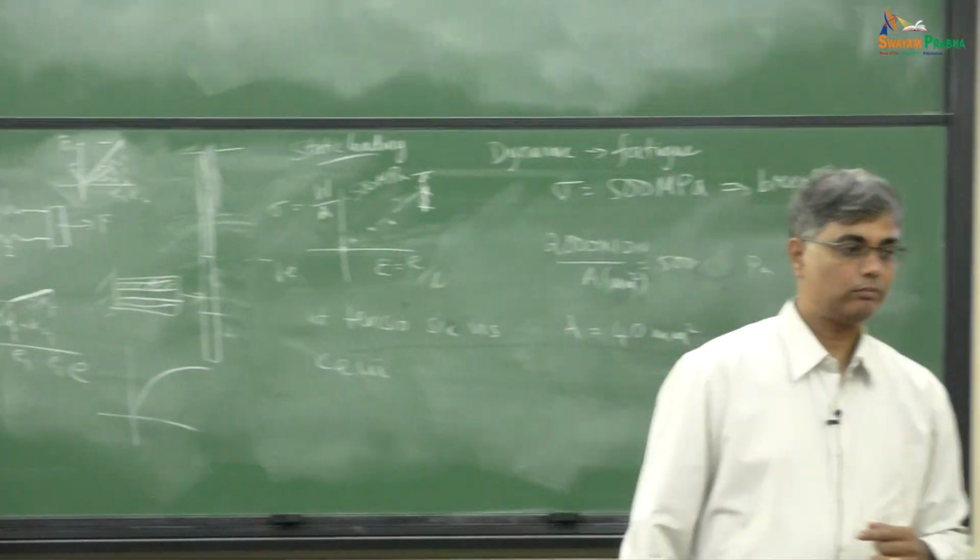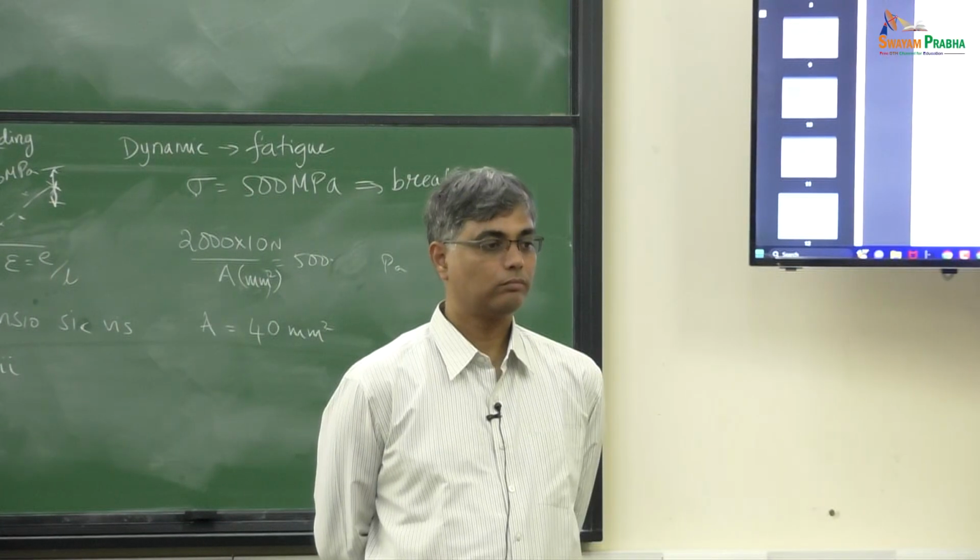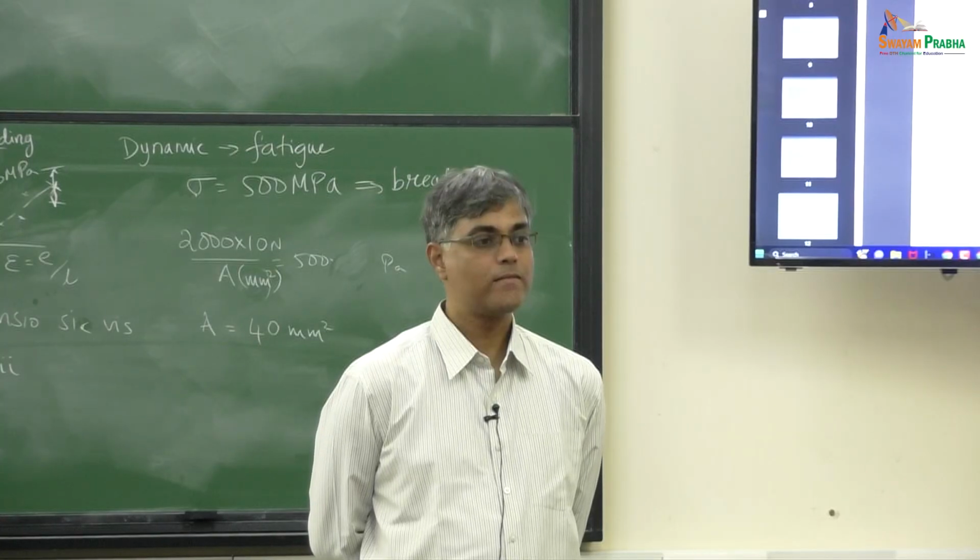Sir, yes, sir. So let's take the 2 springs. To get the extension to be E1, the force must be E1 into K1 plus K2. That is E1 into K1 plus E1 into K2. After that, the first spring breaks. So now only K2 is there and it is E1 into K2.